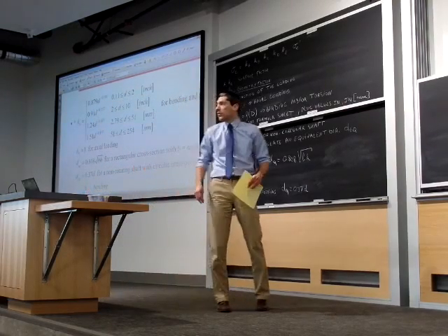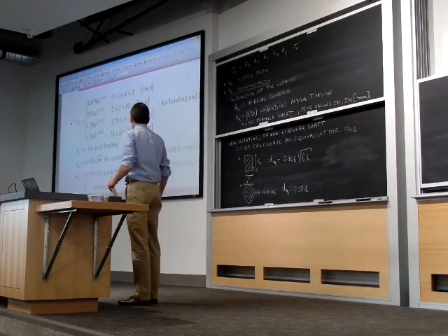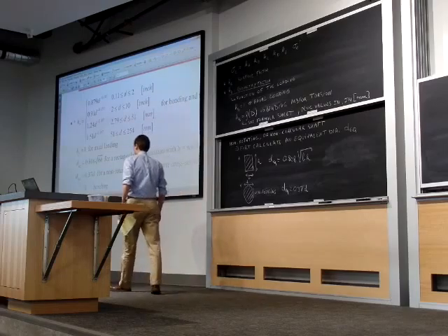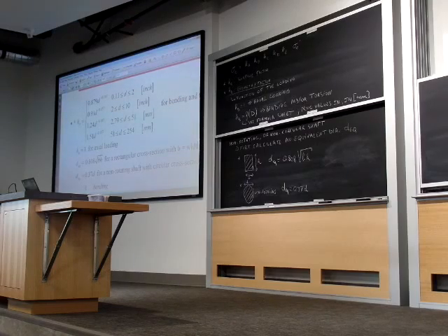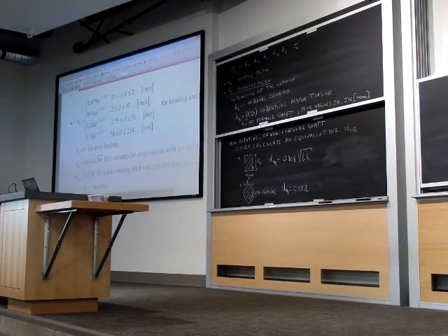Who has a question? Are we ever going to have a hollow shaft? So you got an inside and outside diameter? Yes, and so in case you have a hollow shaft, it does not matter compared to a non-hollow shaft for your fatigue failure. The only thing that matters is whether it's rotating or non-rotating. And the story is again the same. It all depends on where your maximum stress occurs.